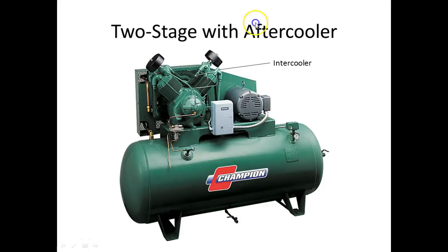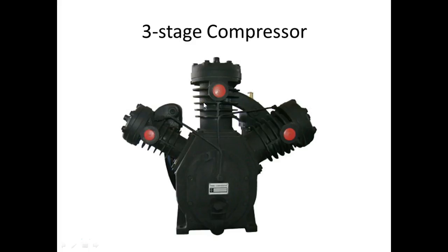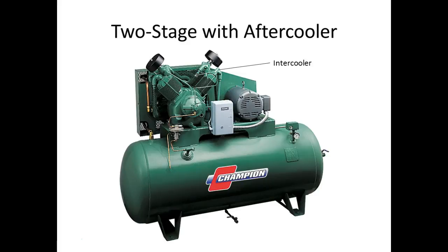Now this is the intercooler. Of course, they're blowing it. This is the motor for the chiller. This is also for the compressor. You can see this cylinder right here. This would be your input, and this right here would be your output cylinder. Can you see they're different sizes? If you look at one and the cylinders are the same size, it just means they get a bigger flow right here. And you see they drop the size down, and that's what they're doing. They're doing this to increase the pressure. Make sense? Okay.